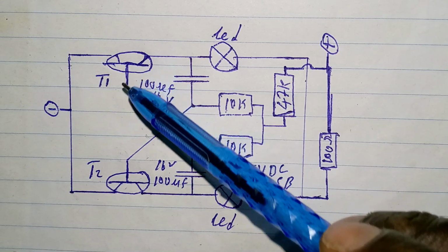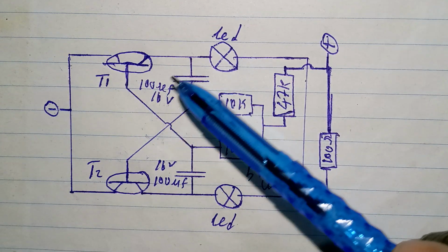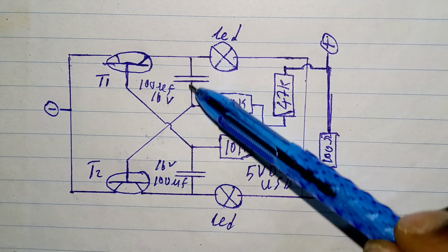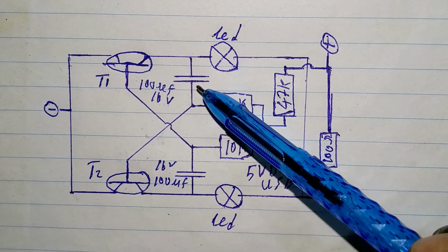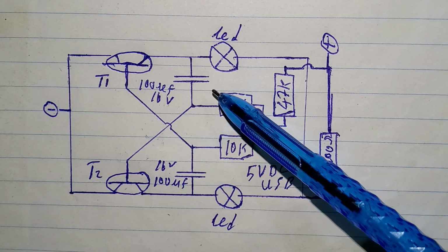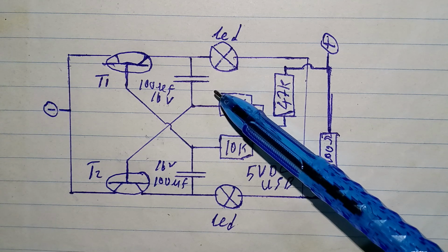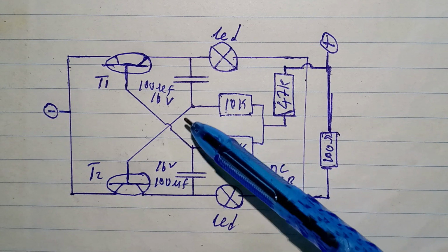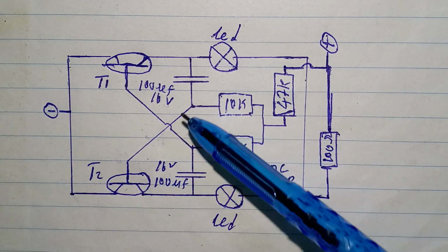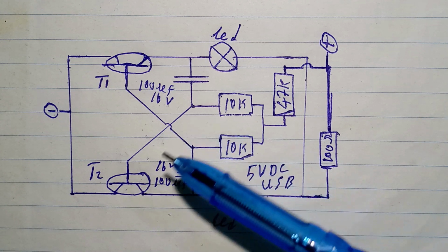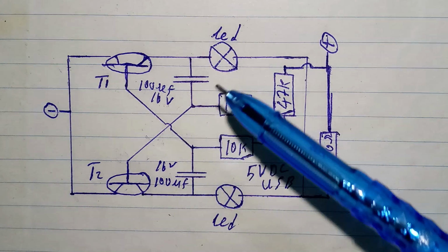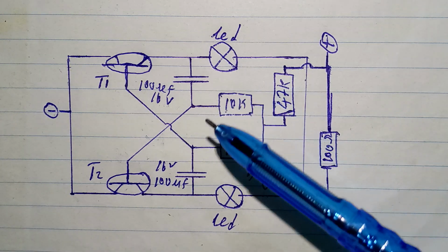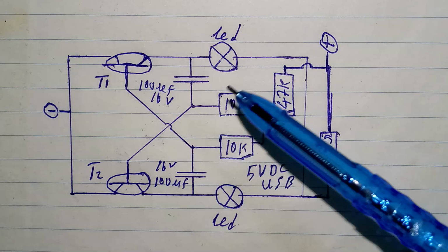It's like they are creating a toggle, and what is actually making the difference is the capacitor, because the capacitors are charging and discharging automatically in the circuit as both transistors switch on and off. That will make the resistance difference. The resistance will be increased and then decreased. That will cause the LEDs or the transistors to be switching on and off alternately.